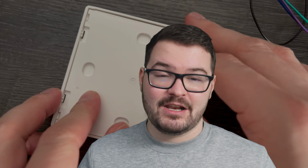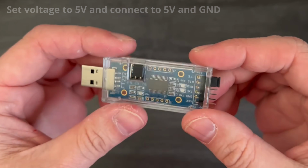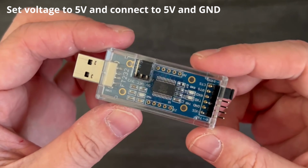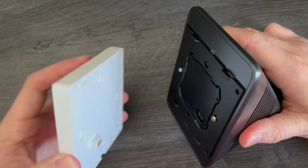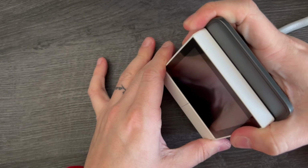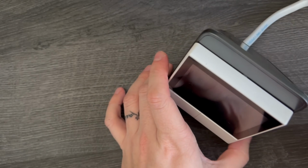We can then power the panel up and we can get started with the next step, and you've got a couple of options for powering it. You can either power it through the mains, or if you're using one of these FT232s, you can actually power it using the 5 volts, connecting it to the correct pins. I'm making use of one of Sonoff's handy little mounts and I'm powering mine through the mains, so I'm just going to connect my panel to the front of that and power it up.